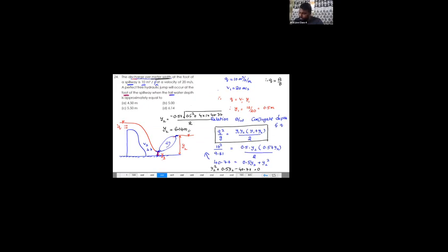So what if the Froude number is 4.5? Is it steady or oscillating? You cannot say whether it is steady or oscillating. It's in between. There's a transition stage, a transition from steady to oscillating. See, the jump cannot suddenly change from steady to oscillating. It's going to transit, and some transition would be there in between the steady and oscillating.